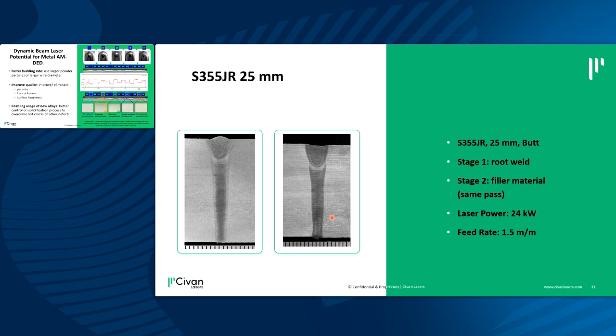They used a sequence of beam shapes through this one hatch, and they more or less positioned each beam shape in the location according to time, where it's supposed to be. You can see the difference in the penetration depth of this hatch by switching between beam shapes. They were also using a pyrometer to measure the temperature within the keyhole and melt pool area. What is interesting is that even though all of these beam shapes used the same power level, the temperature varies and is different because of the distribution of the energy within the beam shape.